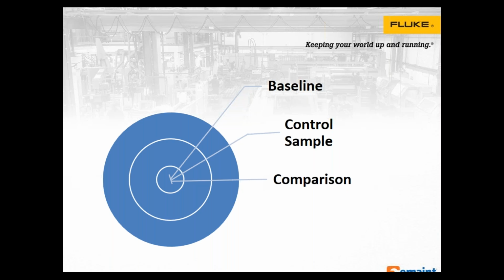And many times the test instruments that they were running the data on for process control and quality control, they were wondering if they were in calibration or not. So they would get a reading every half hour. For instance, at this one site, they would send a sample in of the raw polymer, and they would take several different readings. And sometimes if the reading did not fall within the criteria, the question is, is there something wrong with the output of my instrument that's measuring it, or is it something wrong with the process? I usually felt like I was under a lot of pressure because the instruments I was supporting could change the way they would actually produce the product.